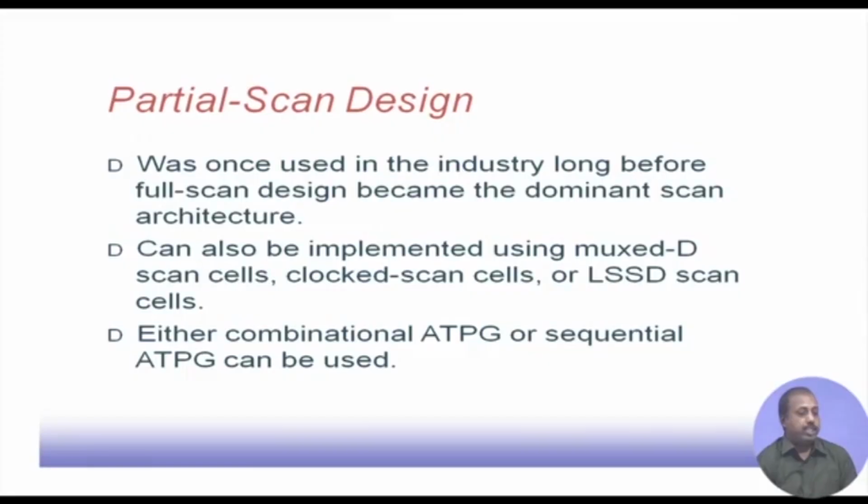Next, the partial scan design. In partial scan design, we consider only a subset of latches or flip flops for putting into the scan chain. The problem with full scan design is that it may not be possible to put all the flip flops or latches onto a chain.